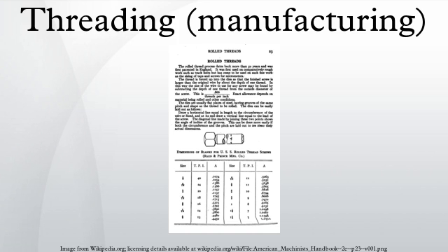To date, most additive methods tend to produce a rough surface finish and tend to be restricted in the material properties that they can produce, and thus their earliest commercial victories have been in parts for which those restrictions were acceptable. However, the capabilities are continually growing. Good examples of threaded parts produced with additive manufacturing are found in the dental implant and bone screw fields, where selective laser sintering and selective laser melting have produced threaded titanium implants.